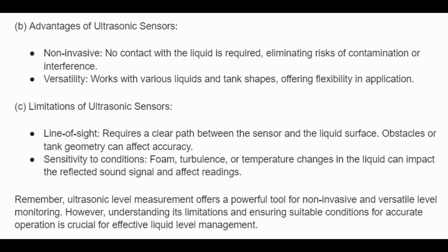C. Limitations of ultrasonic sensors. Line of sight requires a clear path between the sensor and the liquid surface. Obstacles or tank geometry can affect accuracy. Sensitivity to conditions. Foam, turbulence, or temperature changes in the liquid can impact the reflected sound signal and affect readings.